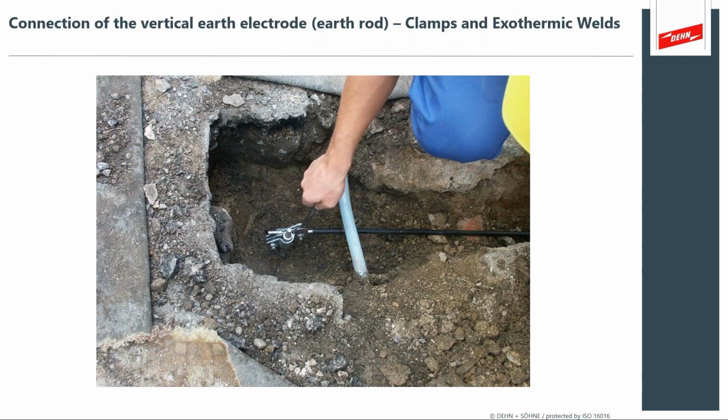So here are a few illustrations showing what that looks like in practice. And even with this one photograph, we could sit down and talk about this for quite a bit of time. Right here, there's a buried cable next to it. Is there proper separation distance? You can see what looks like stones and some concrete around it. So you have to take the actual surroundings into your design to account for what's actually in the system.